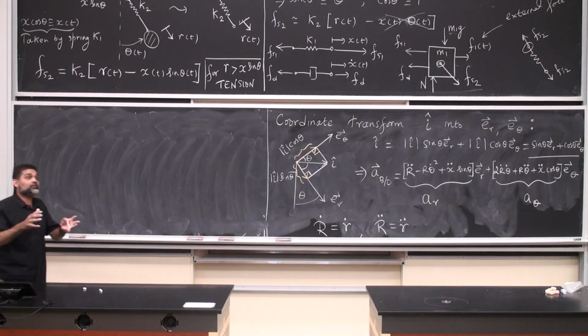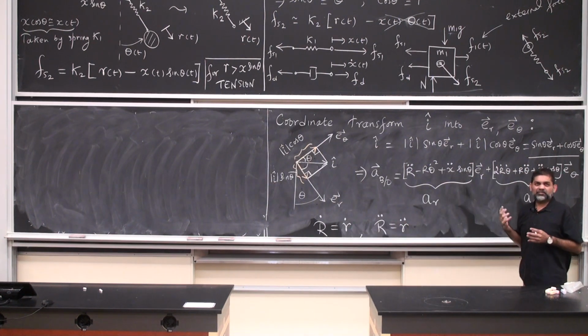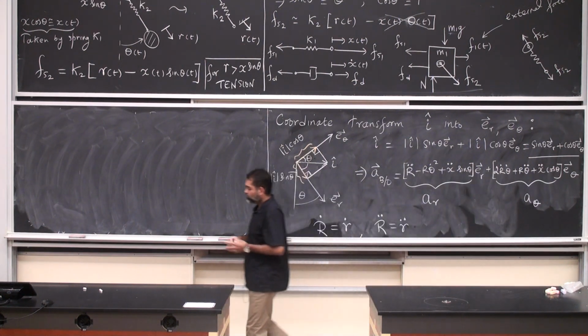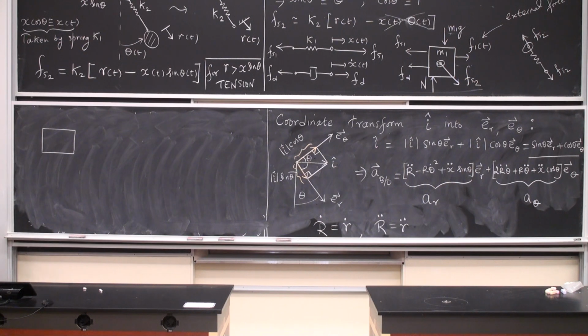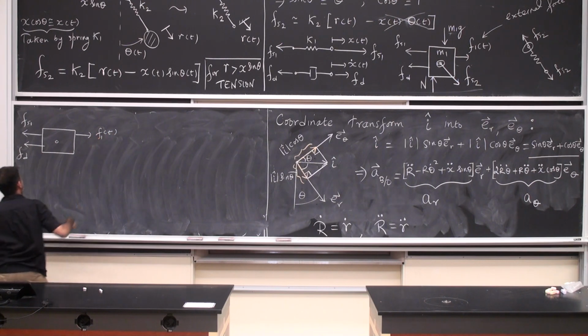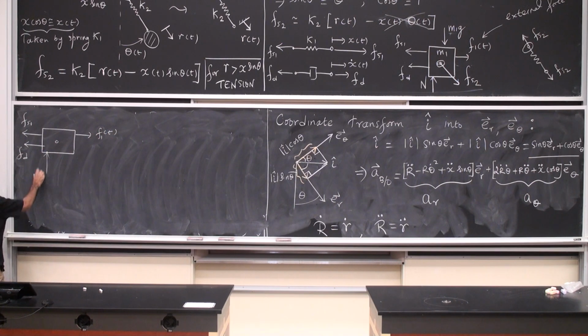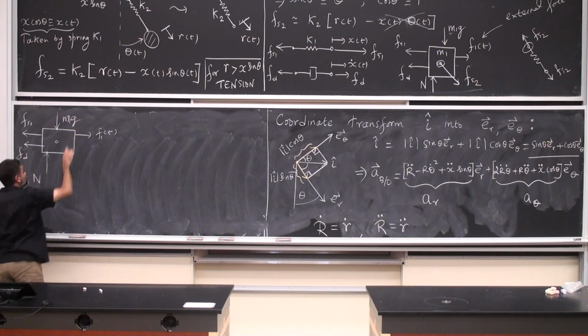Free body diagram of the block, the free body diagram of the bob of the pendulum, okay? A kinetic diagram of the block as well, and kinetic diagram for the bob of the pendulum. So free body diagram. You don't need to write this again because you've drawn this there. Fs1, Fd, F1 of t, normal force, m1 times g.